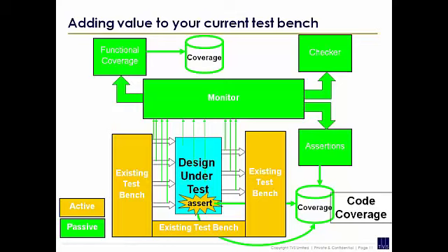Those checkers are very quick to write, and it may be that you can improve the checking on your existing test bench, because if you're writing directed test benches, you have to predict what the expected outcome is. There's a lot of mental activity goes into predicting what the expected output is. And also, what happens a lot if you're doing directed tests, you check what you expect to happen. You don't check that what you don't expect to happen didn't happen.